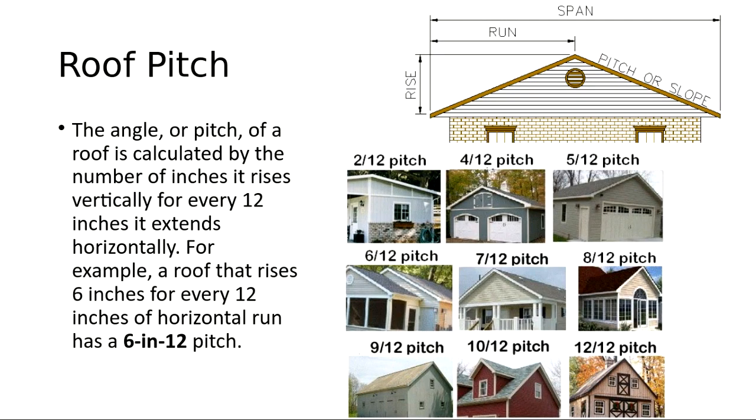Roof pitch. We haven't talked about roof pitch. I know I talked about it in my intro class some. So it's the angle or pitch of a roof. Some of these slides you may have seen from my intro. If you didn't have me for intro, you may not have. It calculates the rise over the run, so it's the number of inches across versus inches up. And you always do it as a number over 12. It's called either the pitch or the slope.